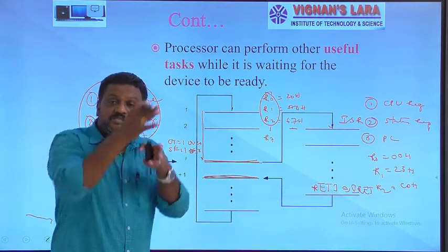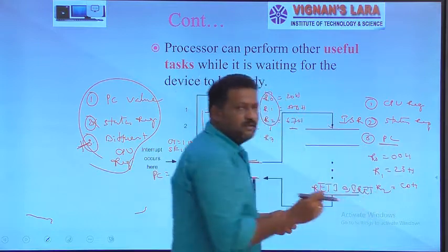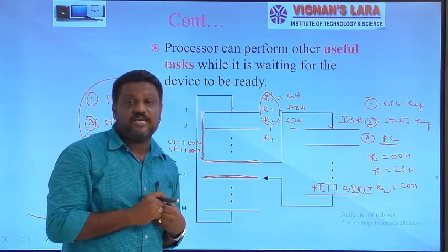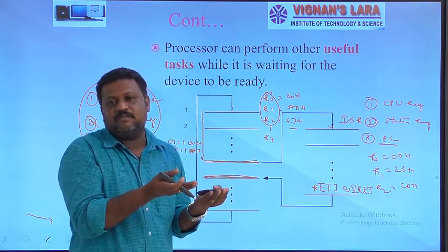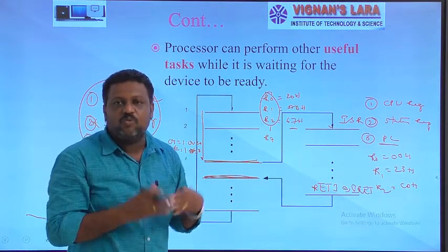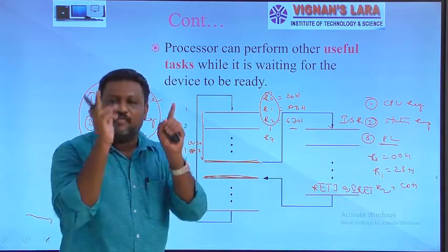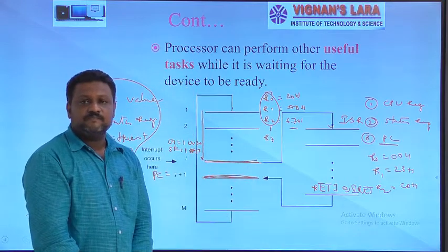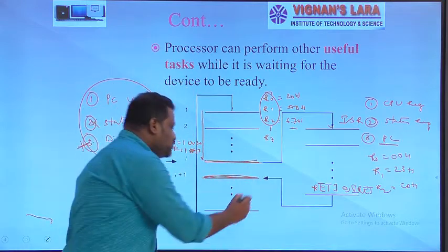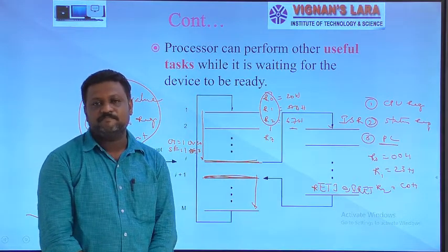Once you are performing the last step, that is accessing the information from the stack, which information are you accessing last? That is the program counter value. Once you retrieve the PC value from the stack, it goes straight to the PC, and only then does the execution change to this. Once we come back to this, we can execute the rest of the instructions continuously.